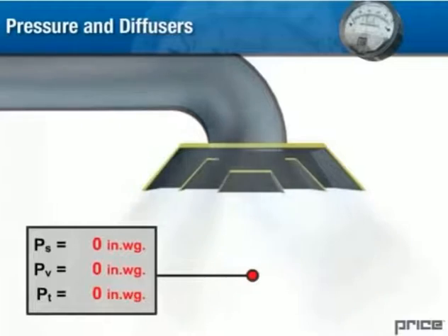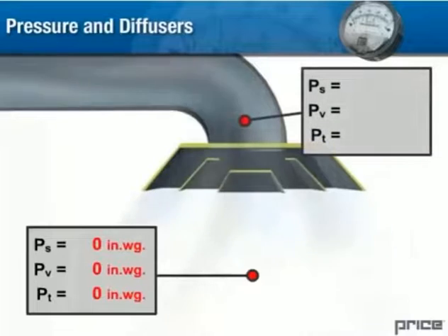Of course, if we measure the pressure outside the diffuser, we will get something close to the environmental pressure, that is to say, a relative pressure of zero. If we compare the pressure found in the neck of the diffuser to the atmospheric pressure, we can determine how much of a pressure drop there is attributable to the diffuser.